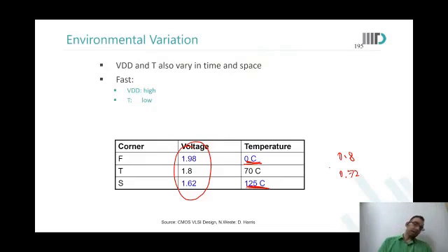So what happens at low voltages, the voltage is so low that the gate overdrive, let us say, is not sufficient. Even if the gate overdrive is sufficient, the number of carriers that you have in the conduction band to be able to conduct the current is not much. There are carriers, inversion is already set in, we know that, but even then there is something missing. As you increase the temperature, more carriers come into the picture. Carriers have more energy now, so they move faster.